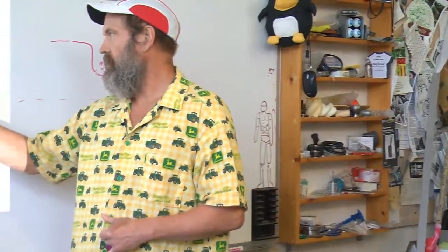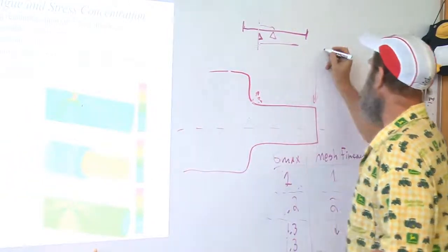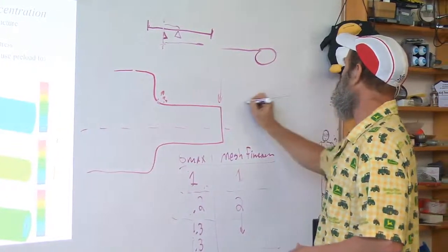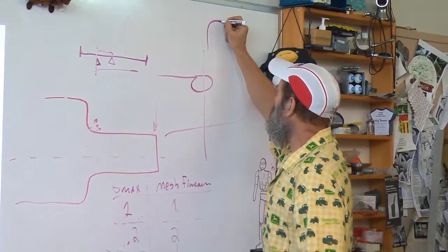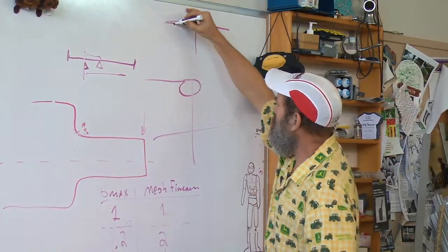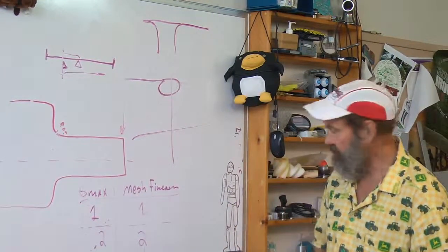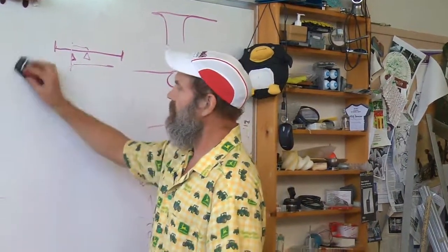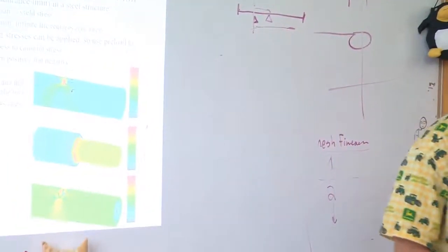Once you do that level of fineness, and now I have, for example, this hole in this shaft, now you can start playing the game of, here's the hole in the shaft. Should this hole, if I do a cross-section, have a nice, gentle fillet on itself? Will that help lower the stress? Keyways on shafts are notorious for causing high stress concentrations. You know, keyways on shafts or holes in shafts.